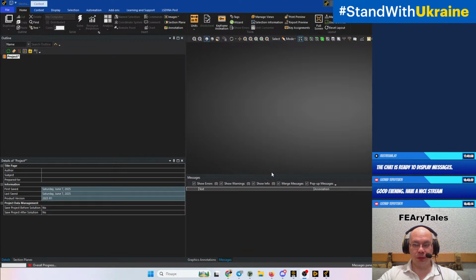So if you see the same type of error about JavaScript and so on during the first running of the new Ansys Mechanical video, in most cases it comes from the need to delete some old junk files from the previous Ansys version, and you can find the workflow of this process on the Ansys forum.